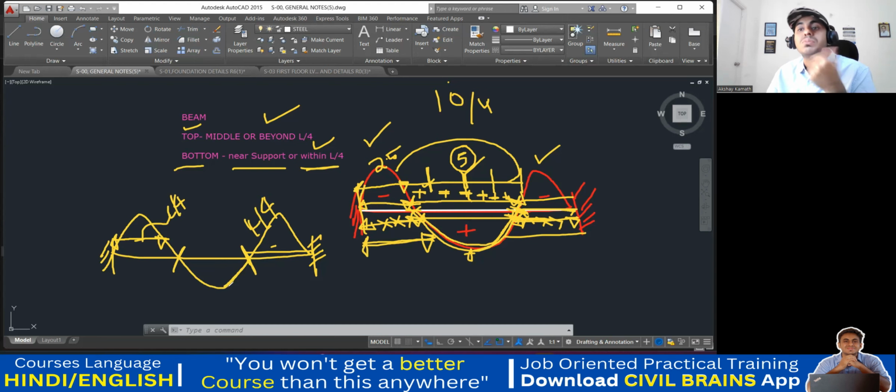So through a lot of beams, we have done the analysis and we have checked it. So that is why we say L by 4 is a standard value that you can take. Now, this may not be true with all the beams. For a few beams it may be L by 5, for a few beams it may be L by 3.